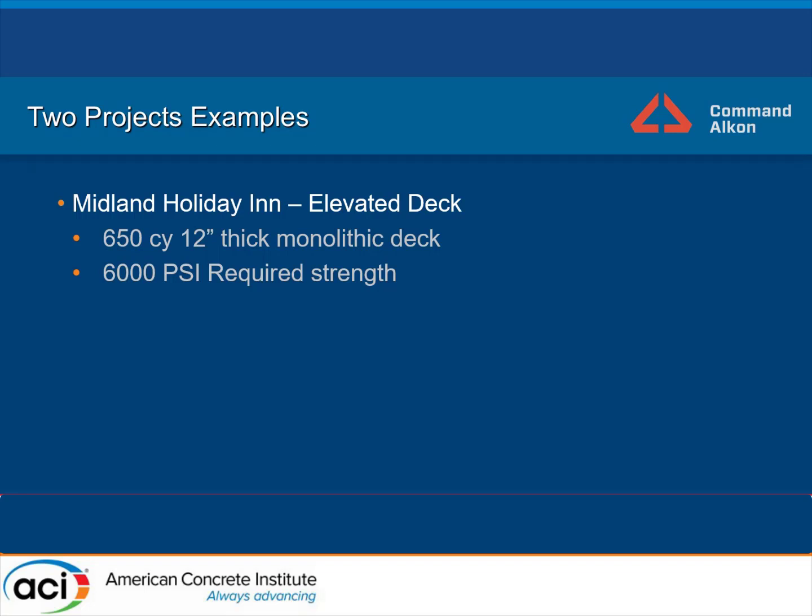Well, we did get to 50 degrees. We tested the concrete. We got 7,800 on average in 28 days. Major success story. I saw times where I needed to talk to the plant manager about a driver, or the field super for me on how it's coming in, and get confirmation of the slump, that it was reading similar to what we said, and everything was going great.